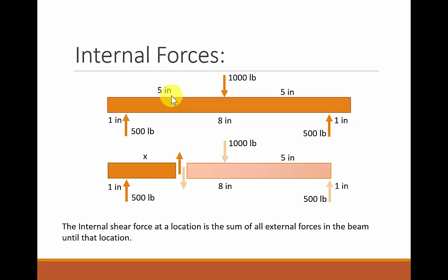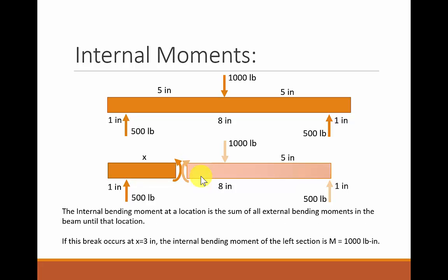And what we're going to say is that there exists some shear force at that location. And so what we're going to do is sum forces. We're going to say, how does this have to be reacting so that this is static at that location? And we're going to see that there are definitely some forces occurring there, and there are some moments occurring there. Okay. So we're going to calculate what those are, and we're going to use that to figure out what the stress is at that location.